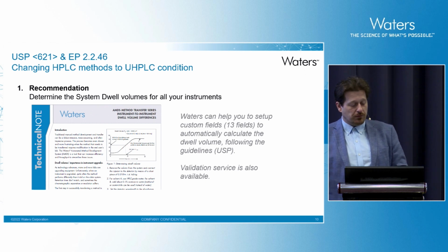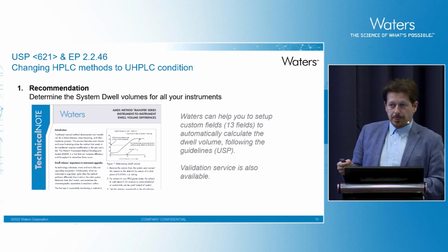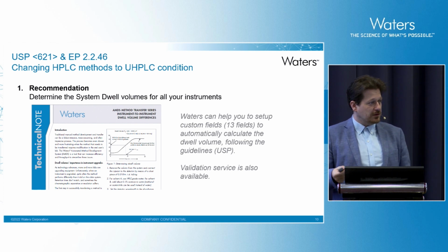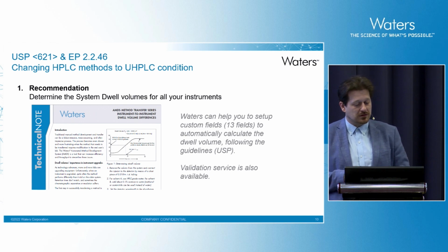And if you know, okay, my flow rate is 1 milliliter per minute, and it arrived 30 seconds delayed, then I have 500 microliters volume difference. Yeah, this is how it's done.